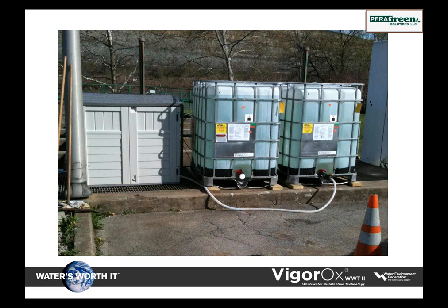But if you see, it's a very simple system. We're feeding out of totes. Our pump was in the doghouse on the left. We fed 25 feet ahead, and we flow paced the pumps. That's all that was required to run the evaluation. The state came by. They approved the application because of the way it was contained over the basin, and we fed the product and let it flow pace based on north and south contact chamber flows. But again, you don't need elaborate feed equipment. It's very simple to apply. The key is keep it simple.